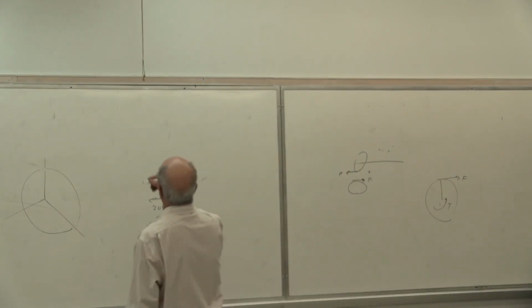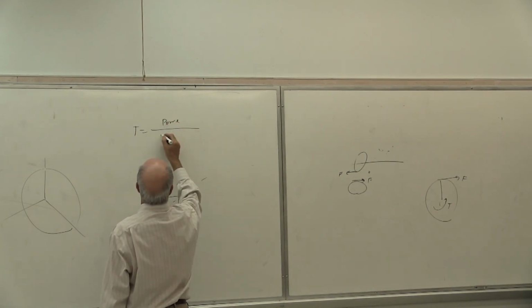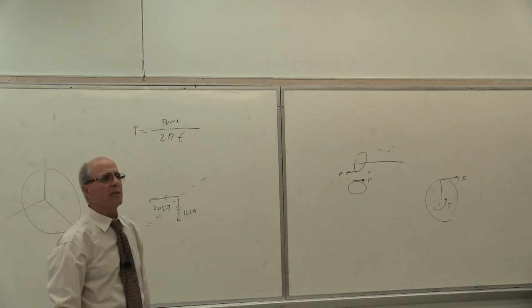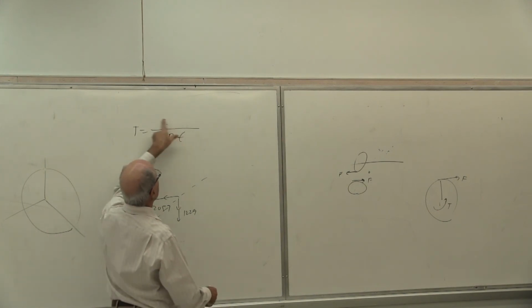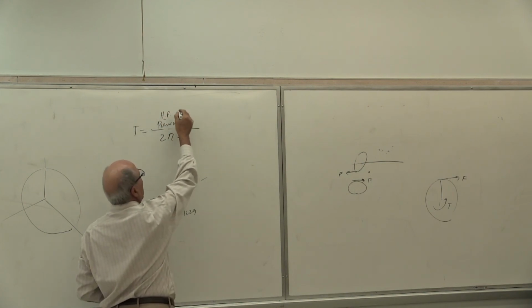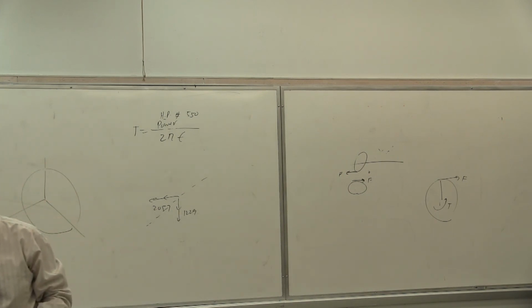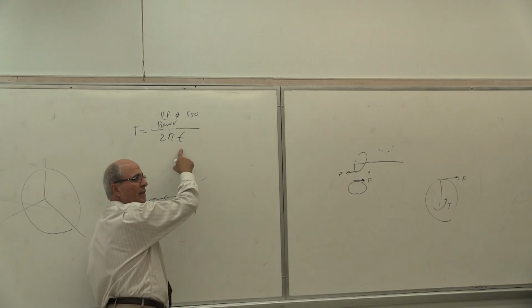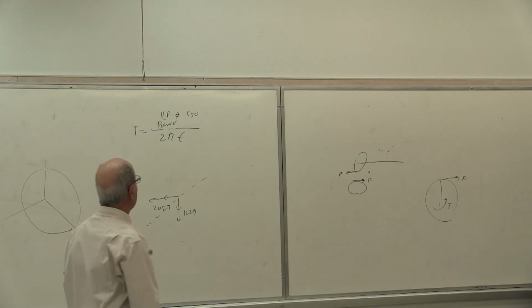The other part is that you know the torque equals what? Power divided by 2 pi f. Remember that equation, yes or no? Yes. But if power is in horsepower, one option is you multiply it by 550 pound-foot per second. It's all in your notes, in your ME218 analysis, yes or no? And then f is revolutions per second, not RPM. So you use those two ideas to calculate forces.